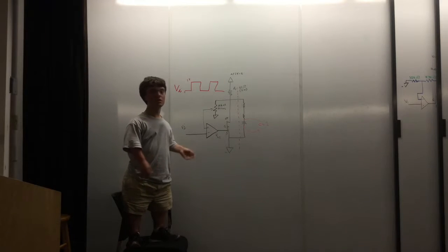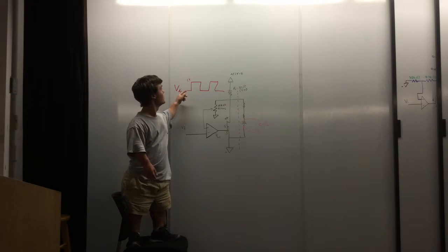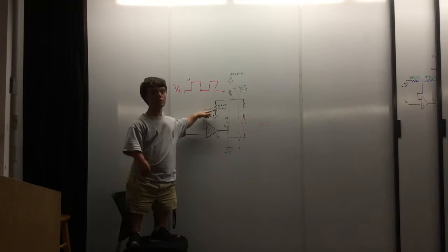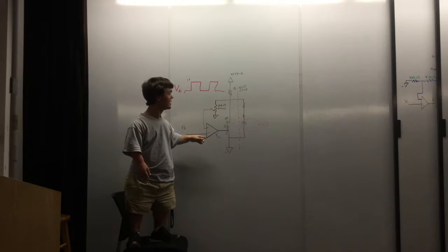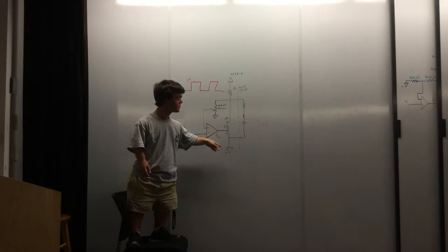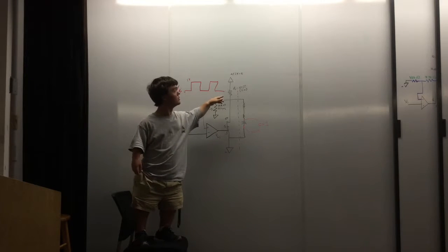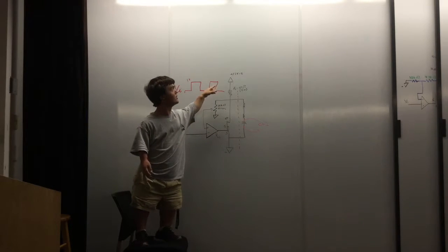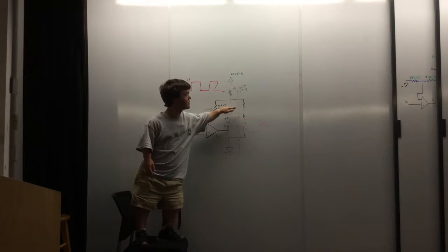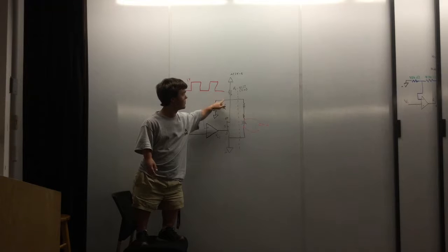So we initially start with this circuit where we have an OP amp comparing the voltage in, which we had as a 1 volt square wave going from 0 to 1 volts, and it was also comparing the voltage from a 10 kilo ohm 10 turn trim pot, and now it's connected to the gate of a MOSFET transistor. The source of the transistor was connected to ground, and the drain was connected to a 10 ohm 2 watt power resistor, which was connected to 5.2 volts of DC. And this was all connected to the resistor, inductor, and capacitor in series. So this was in parallel to that.